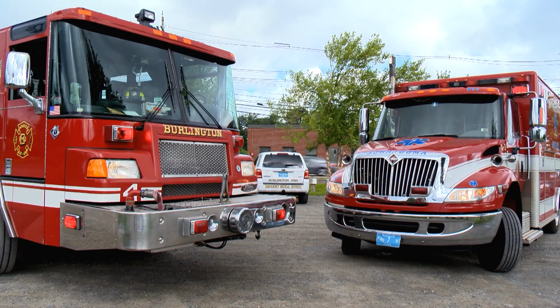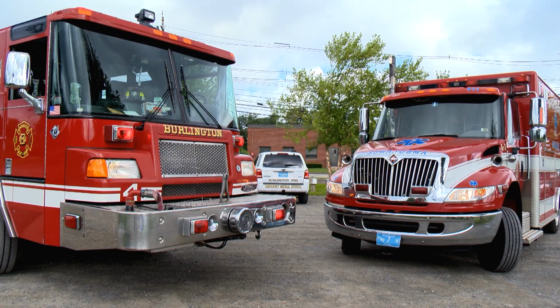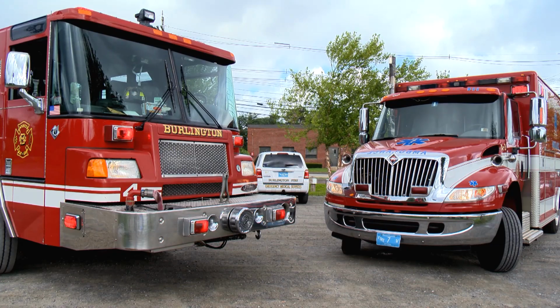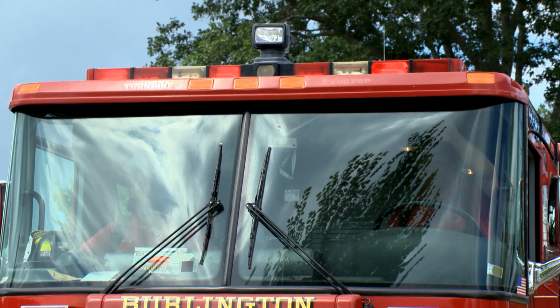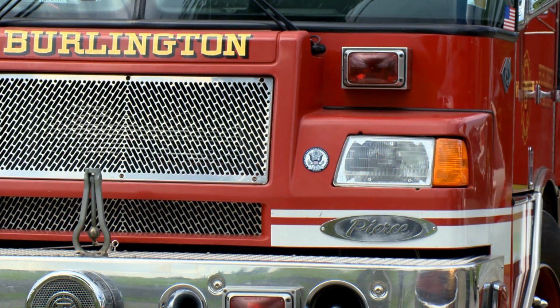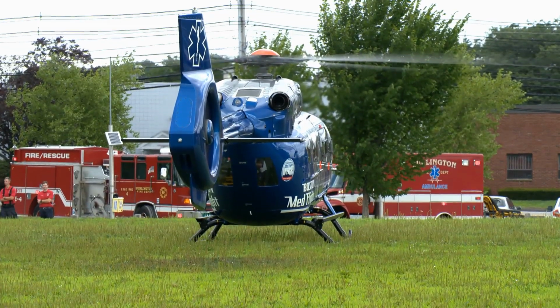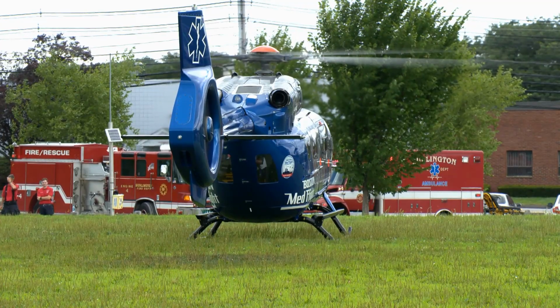Make sure all vehicle emergency lights are always on to assist the helicopter in locating the LZ. However, if requested by the pilot, be ready to turn down or off the emergency lights. Do not point spotlights at the aircraft while in flight or landing.